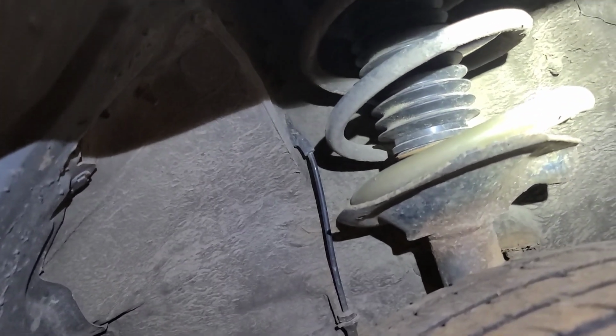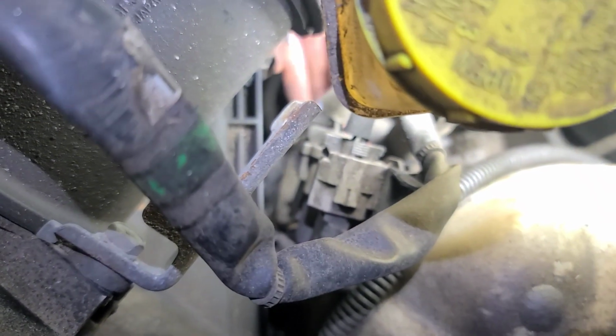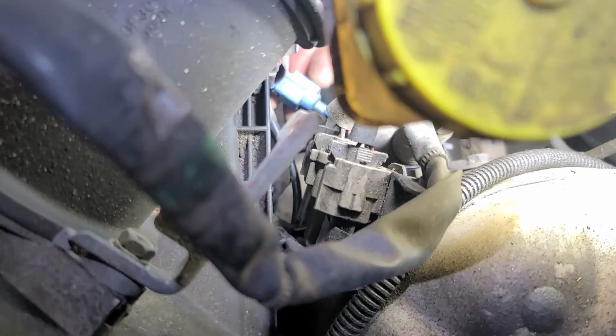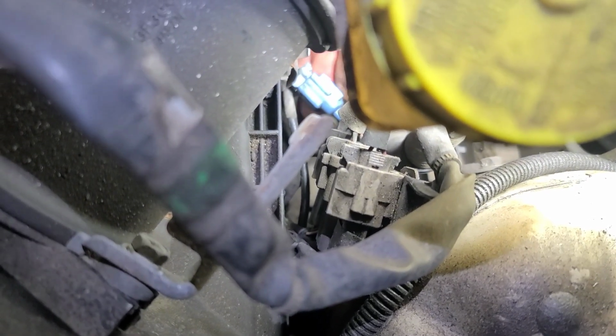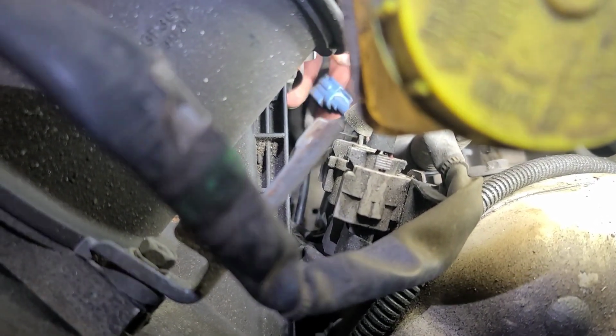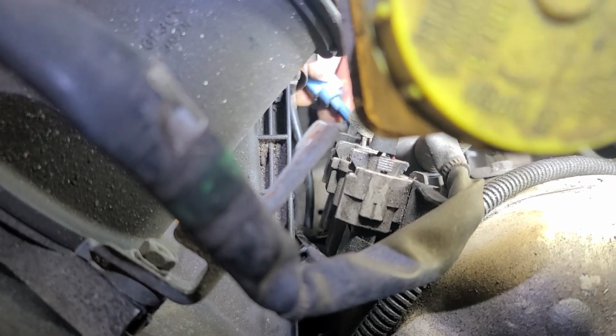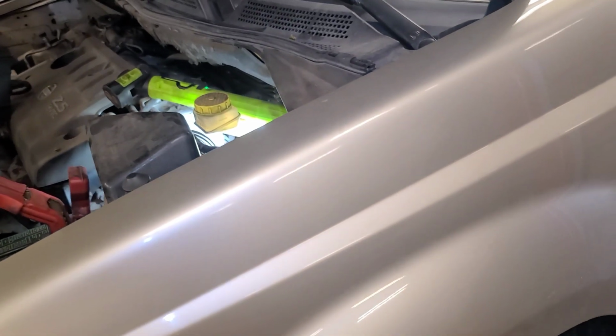So the speed sensor wires go up through the strut tower and into the underhood area beside the airbox. You see that blue connector down there? Right down here, that is the speed sensor connector. So I'm going to unplug this and try and pull the harness through the wheel well so I can get at it. And then we'll do some resistance testing on it, assuming that it's magnetic pulse.